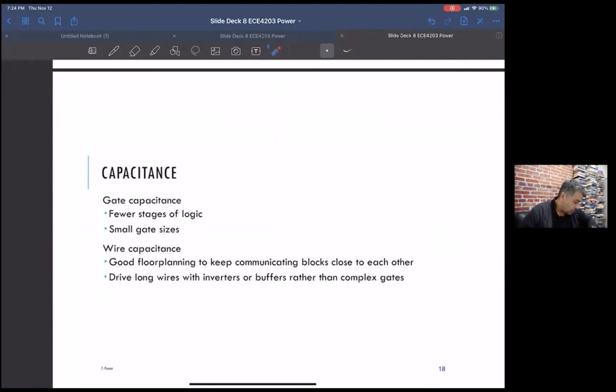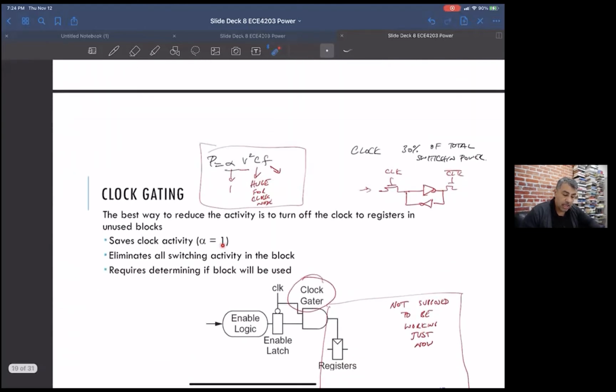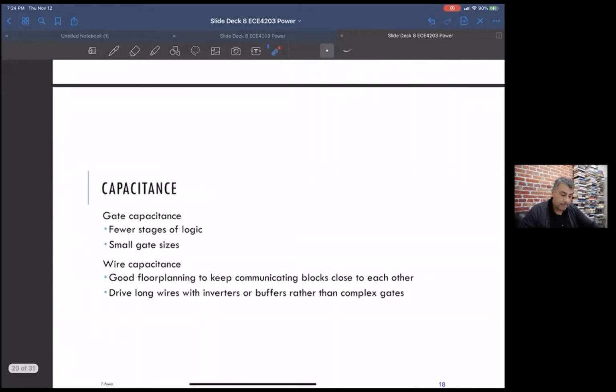Okay, so the next thing. That was the clock, basically reducing essentially the capacitance or activity factor, really. So you have a high activity factor thing, and on average you're reducing the activity factor when taking over the entire chip. Okay, so the next thing is the CV squared F. I'll write this because I never get tired of writing this. CV squared F. So, looking at the capacitance.